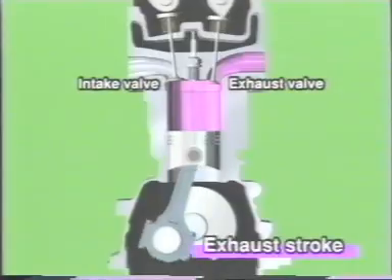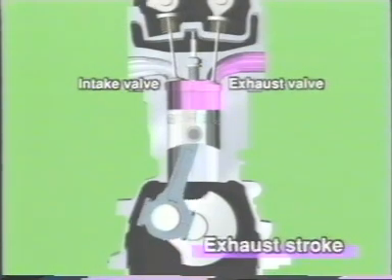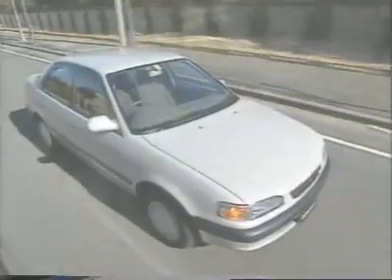At the end of the piston's downward stroke, the exhaust valve is opened. As the piston is again raised, the combustion gas is expelled from the cylinder through the exhaust valve. In this way, the crankshaft rotates 2 turns while the piston moves through the intake, compression, combustion, and exhaust strokes. The engine continues running by repeating these 4 strokes of piston operation, thereby driving the vehicle.